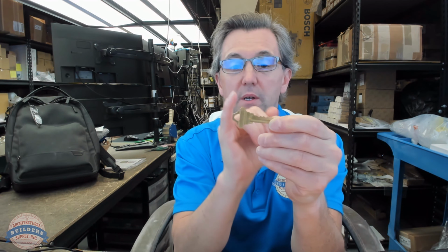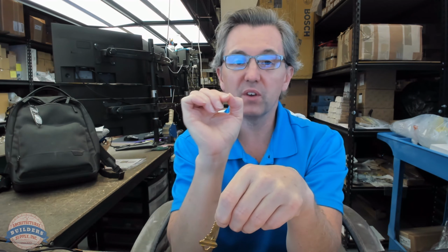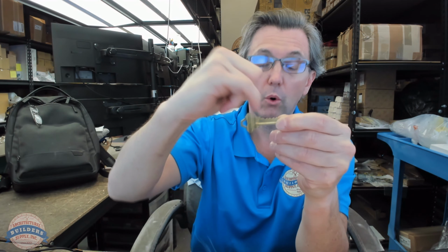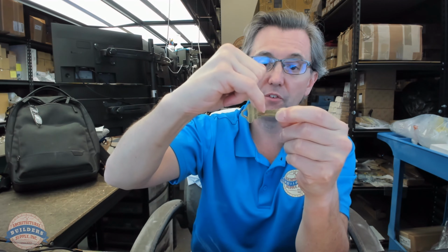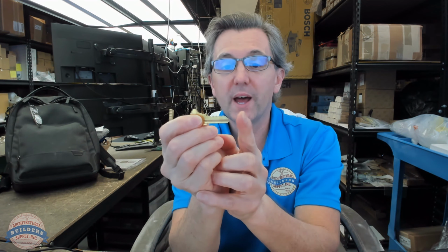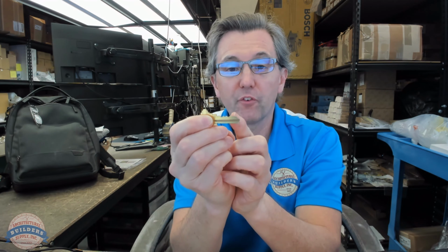The third thing that makes it particular is the spacing. So if I went from the center of this cut to the center of this cut, that is a very specific spacing, as is the shoulder or the stop. This has a shoulder stop to the first cut. If it was Best small format, it would be from the tip stop to the first cut. That is the spacing. So the shape of the cut, the depth ranges, how does a 2 differentiate from a 3 in terms of a value, if you measured it with a caliper. And then the same logic for the horizontal spacing, so your X and your Z, I suppose.